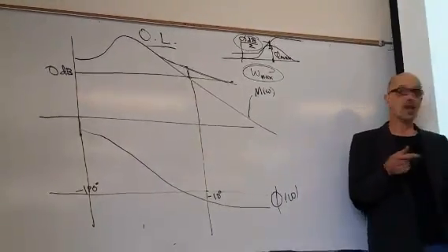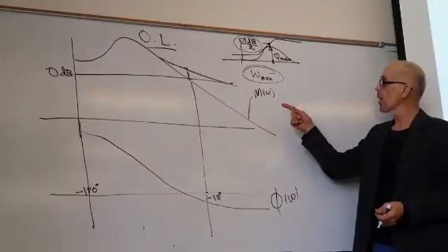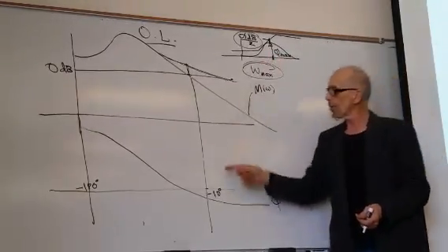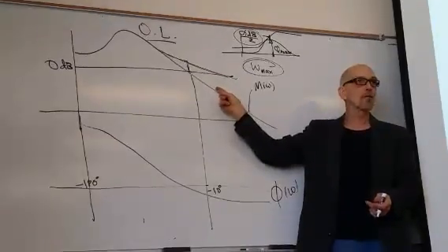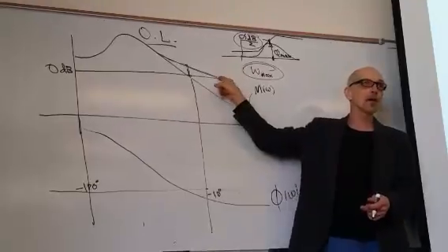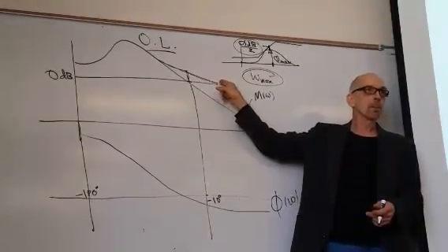Following? Then you say, well, where do I want to put this omega? Where do I want to put my compensator? Well, I want to put it where the magnitude is currently down alpha dB over 2, because I know it's going to raise it up alpha dB, and that's going to be my crossover. All right?